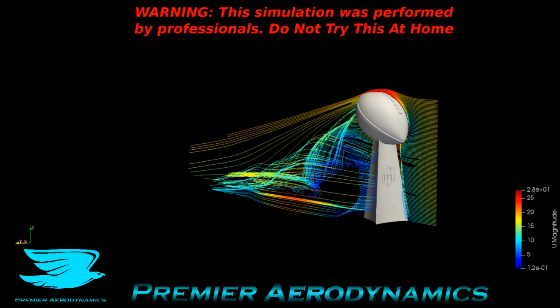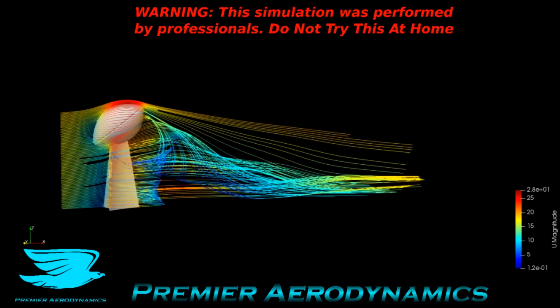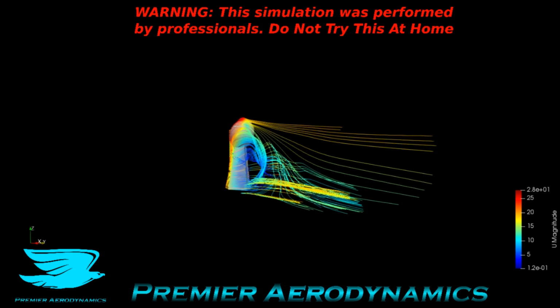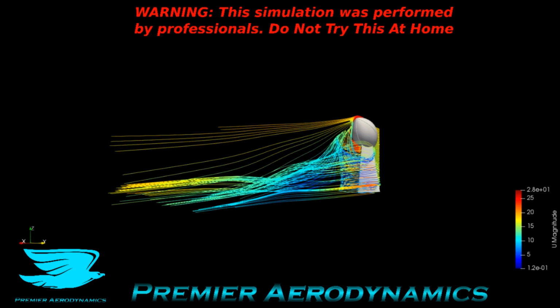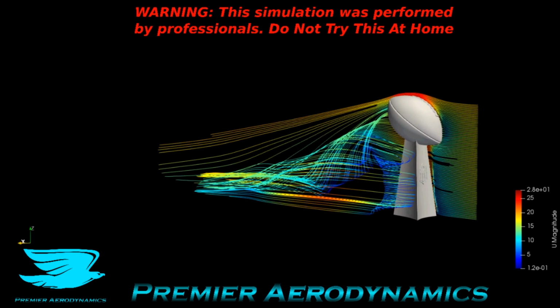Even though it looks fairly streamlined, like the football, the trophy bit isn't that streamlined, but it is fairly sharp in some places. It does taper around, but because the front is so wide, that creates a lot of wake, and this creates a massive structure behind, and it's very chaotic. You have all these different roll-ups from different areas, and there's a lot of unsteadiness.